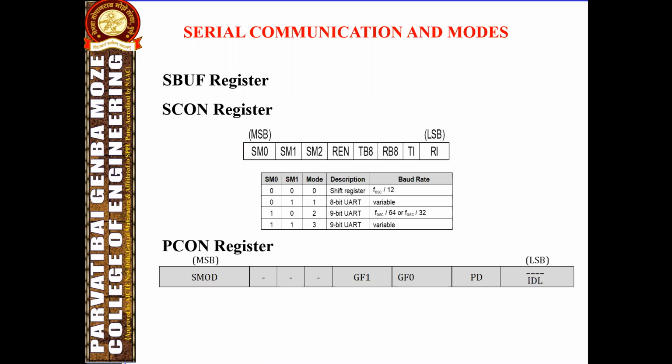First of all, we will see what serial communication is and what happens in serial communication. In serial communication, the data here is 8-bit in the 8051 microcontroller. The 8-bit data byte must be converted to serial bits using a parallel-in serial-out shift register, and it can be transmitted over a single data line. At the receiving end, there must be a serial-in parallel-out shift register to receive the serial data and then turn it into a byte.